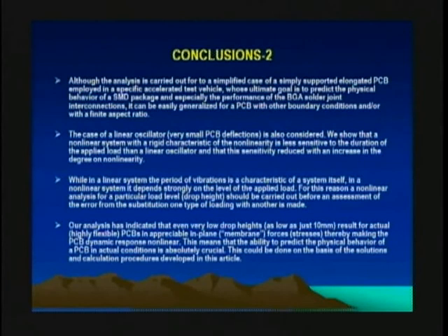While in a linear system the period of vibrations is a characteristic of the system itself, in a nonlinear system it depends strongly on the level of the applied load. For this reason, a nonlinear analysis for a particular load level, drop height, should be carried out before an assessment of the error from the substitution of one type of loading with another is made.